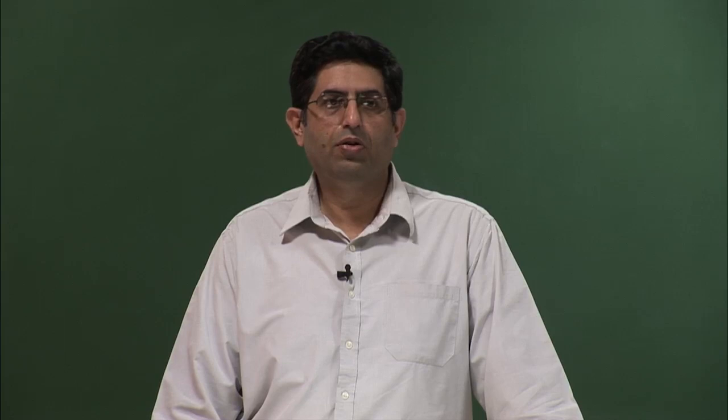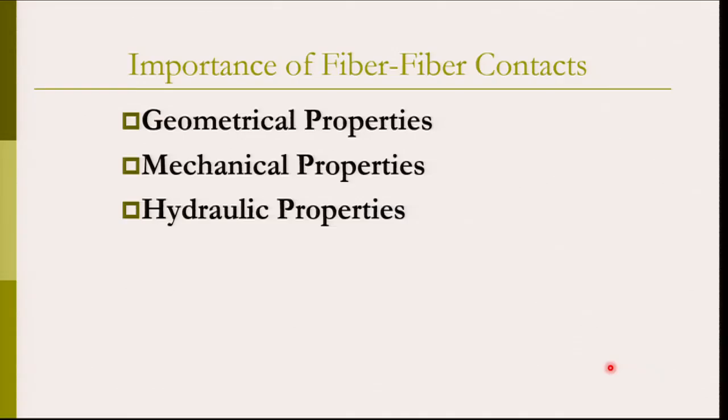So, if there are no contacts formed between the fibers, then the loads will not be effectively transferred from one fiber to the other fiber. Hence, you can see that there is a significant importance of fiber to fiber contacts in influencing the mechanical properties of these materials.